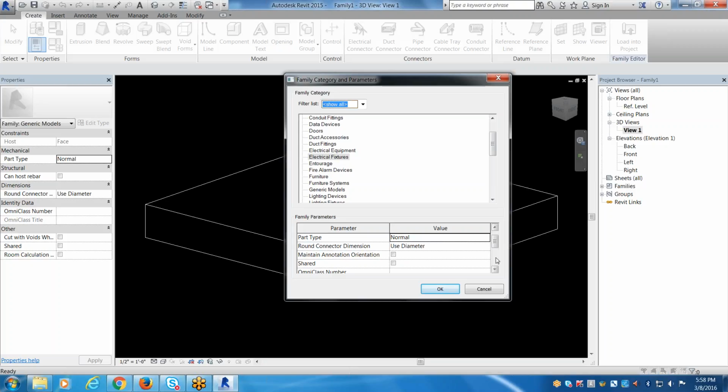That annotation is always like this. So is it going to turn with the object, or is it going to maintain and always be visible? This has to be checked. When we're creating electrical symbols or anything where we have nested annotations, we have to check this box. I know this might seem crazy, but in about 30 minutes, we'll have the whole thing complete.